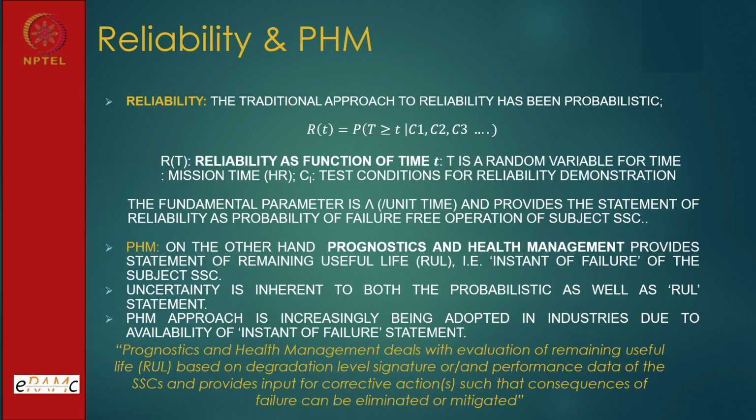That means if a component fails, the plant has to be shut down or derated. Now for certain components, a lot of redundancy is built in and we don't depend on the one component. But then there is the allowable outage time. Let us say one piece of equipment went out of order during plant operation. Our plant specification says that even though you have redundancy and diversity, its allowable outage time is 8 hours.